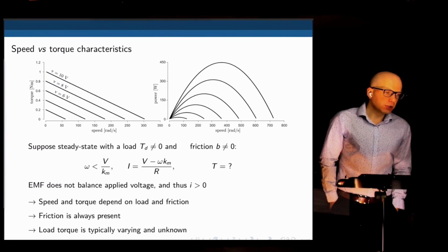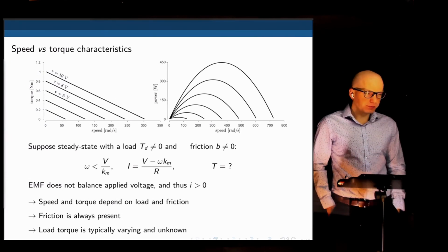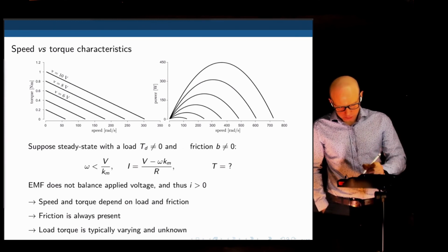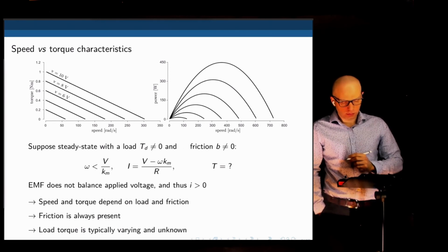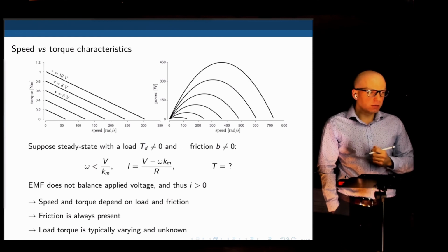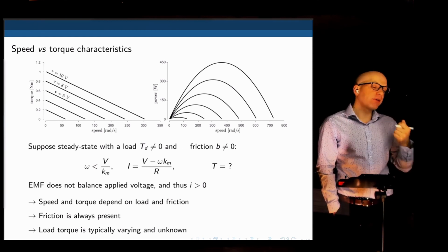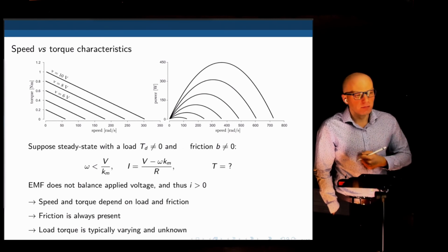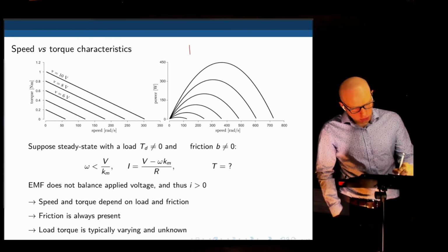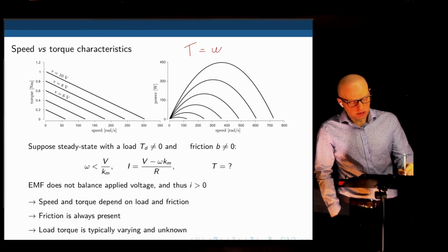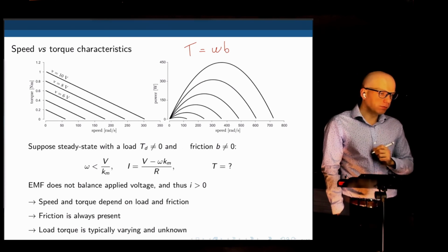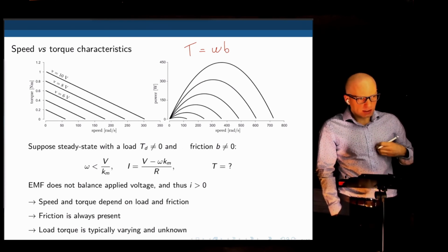Before we go into position and speed control, are there any questions? Can you just explain that last part again, what you said about the viscous friction? For speed, the only thing that is the limiting factor for the maximum steady state speed is the coefficient of viscous friction, because the only torque opposing motion in the absence of a load is the speed times the coefficient of viscous friction.